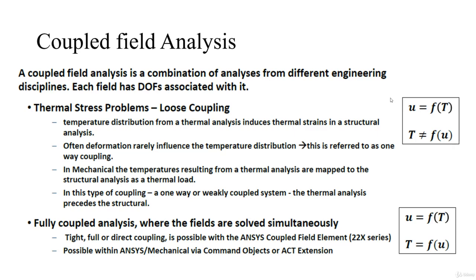Loose coupling. So what does loose coupling mean? Temperature distribution from the thermal analysis induces thermal strains inside the structural analysis. Due to the temperature distribution inside the body, which is calculated from the thermal analysis, these thermal strains are taken as an input into the structural analysis. Often, deformation rarely influences the temperature distribution, and this is referred to as one-way coupling.